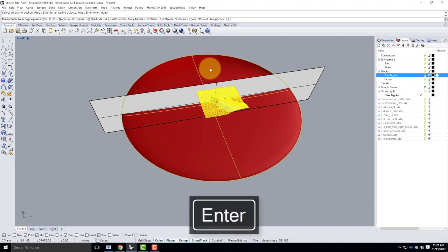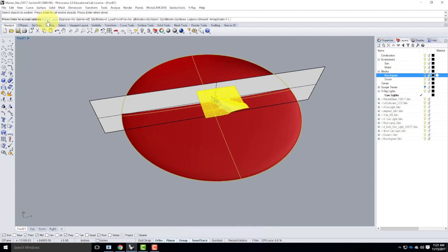I'll press Enter. And then it gives me options. So what direction do I want it to be? The x-axis or the y-axis? In this case, I want it to be the x-axis. You can do a section that's on an angle, but it's a little bit more involved. You have to establish what the angle would be from point 0, if you're going to do that. If you want to, I'll help you through it, but it's not worth spending time with everybody doing it.